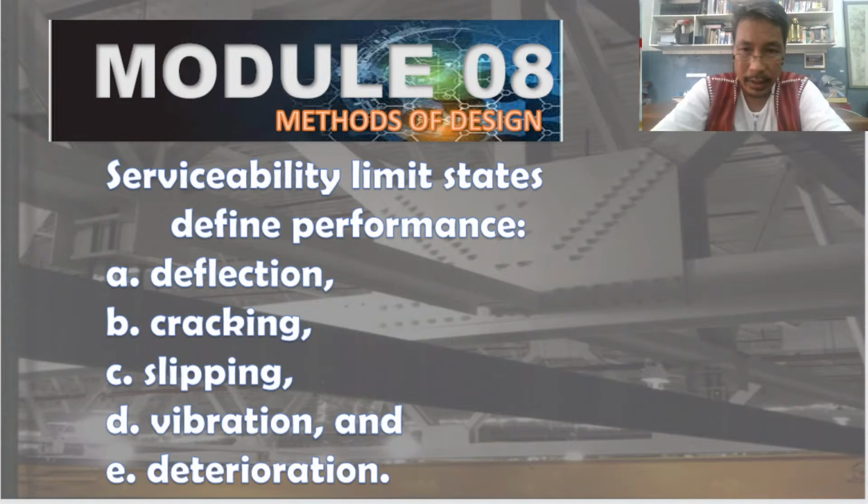What about SLS or serviceability limit state? We can design the system against, number 1, letter A, deflection. Letter B, against cracking. Letter C, against slipping.